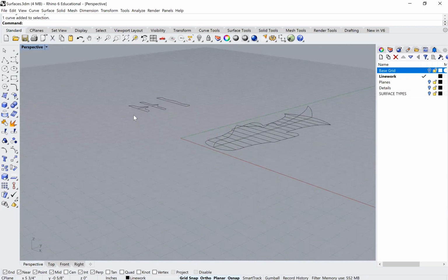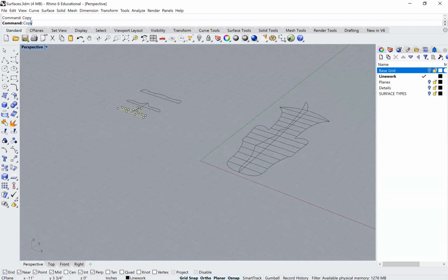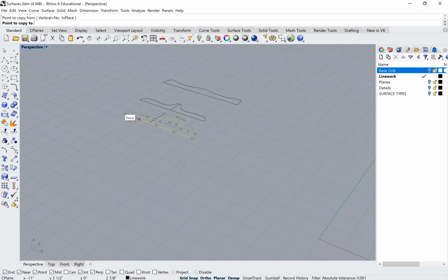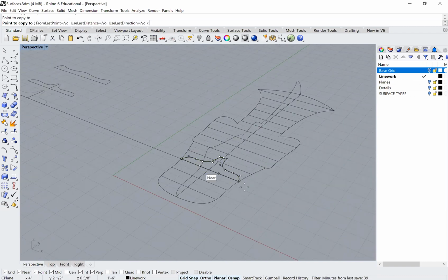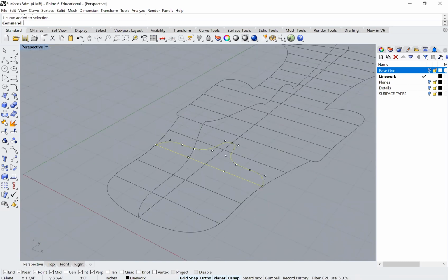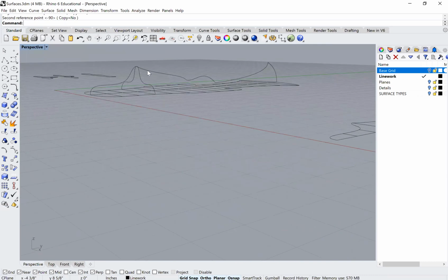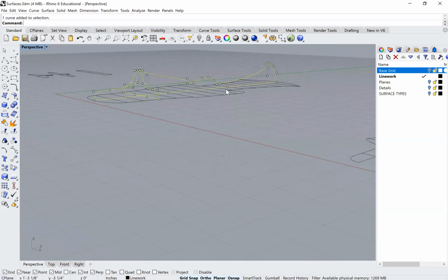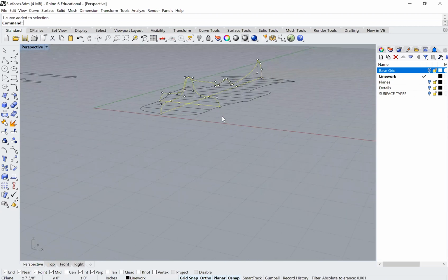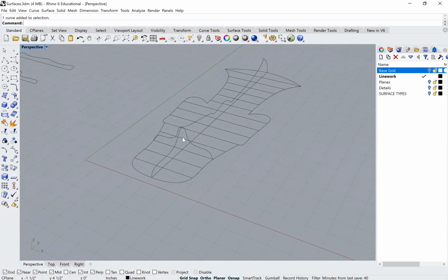And so if you can see now, I could actually grab this thing, copy it over exactly at that endpoint, and copy it to that exact location. And you can see that it matches perfectly with this edge and perfectly with that one. And I can rotate it 3D along this axis, once again 90 degrees. And you can see now that we're starting to create sort of that network surface that is kind of the information, the ISO curves in a way of this mask, of the surface that makes up this mask.